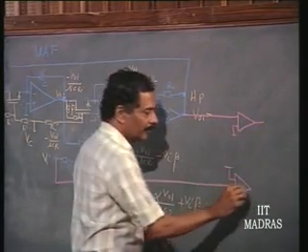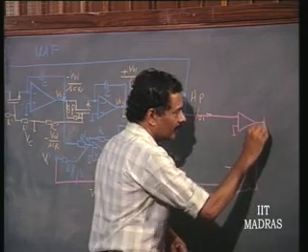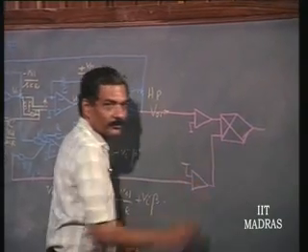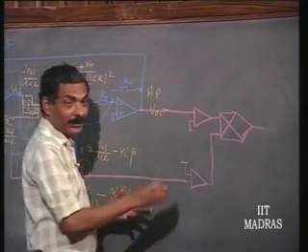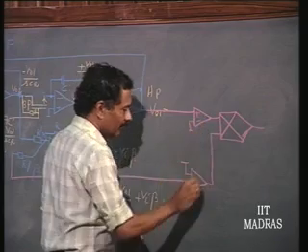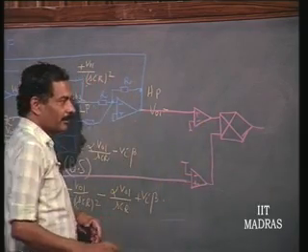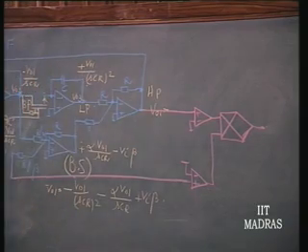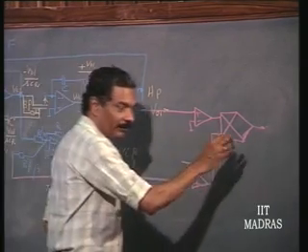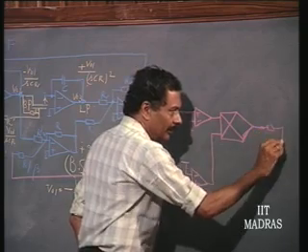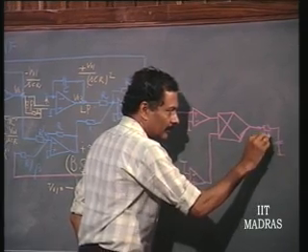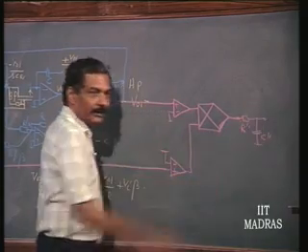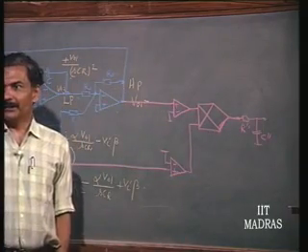And how is the phase detector simply designed? Let us say we put a multiplier, right, a linear phase detector I am putting. We do not have to put a linear phase detector, but for simple analysis it is fine. So, we have put a linear phase detector now. It will become a phase detector primarily when I take the DC out of this. So, this average will tell me whether it is tuned.